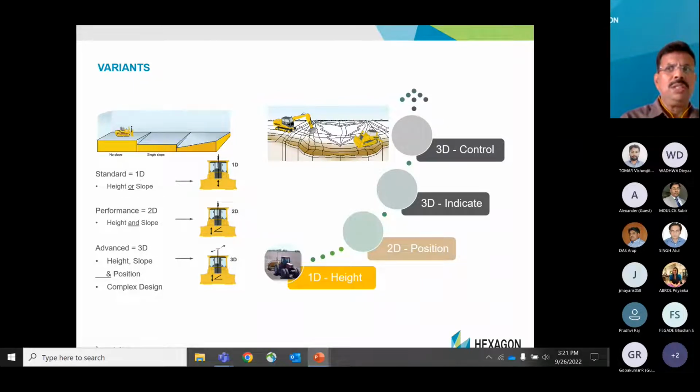In India, using this 2D technology on roads is a little bit difficult. If you consider 200 meters as a single stretch, it will be difficult to get such a flat surface, either horizontal or sloping upward or sloping downward, for more than 20 to 25% of the whole project. So ideally, for road construction work, we have to go for 3D. Then what is 3D? 3D addresses everything, but you need to have a design.